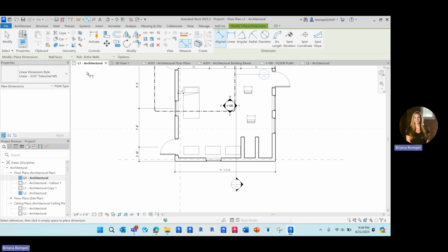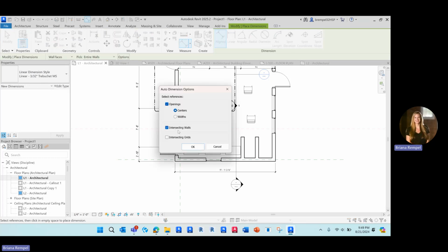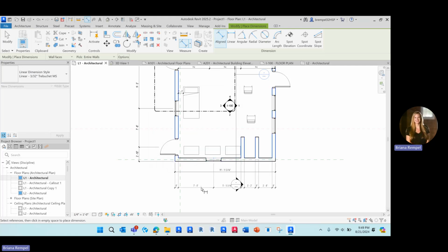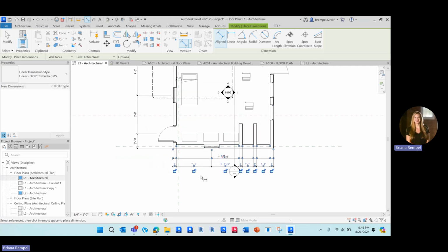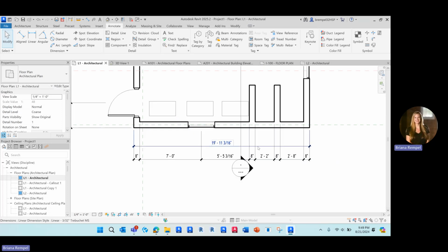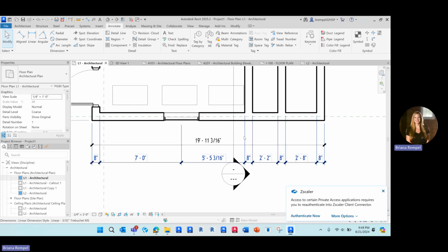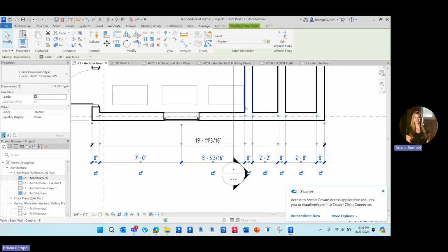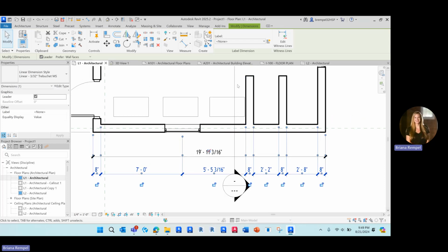All right, let's try that again. Entire walls, options. I'm going to make sure that's set to include intersecting walls and openings. Click on that wall, and it's automatically going to generate those items. Typically, you wouldn't dimension like this on either side of the wall just because you don't want to over constrain it. The wall width would come about from a wall type.